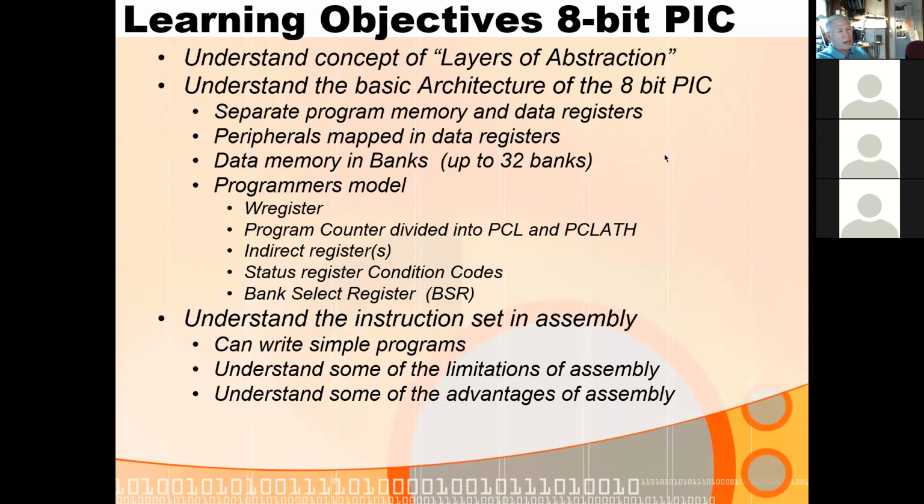So they'll do things like average so many values and things like that. And with these ADCC modules, they wrote assembly language instructions to implement the touch sensing application. So they don't even actually have a dedicated module. You just use the A to D converter. I haven't implemented it on this. I haven't changed chips, partly because of that. That's one of the things that's kind of caused me to stick with this chip.